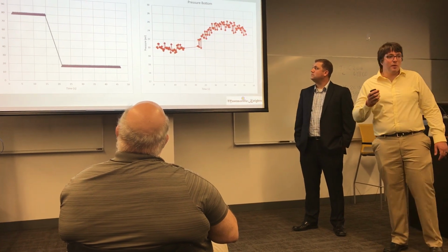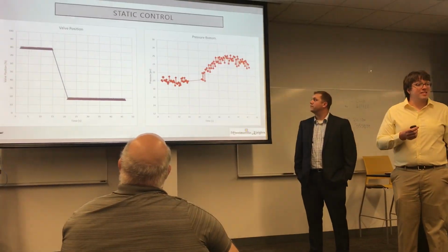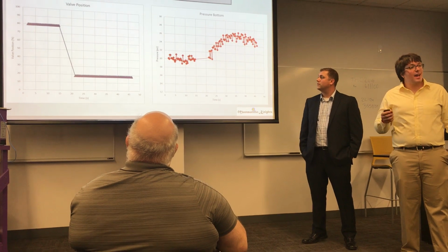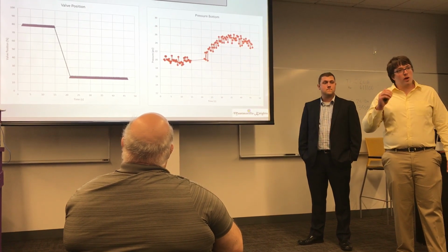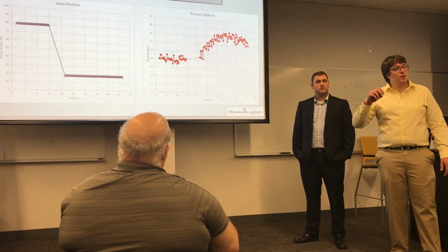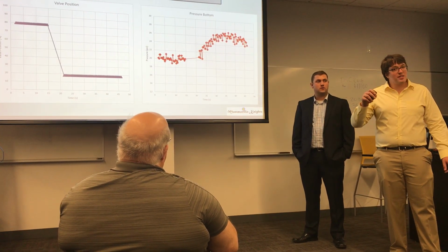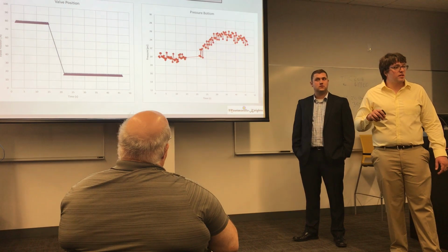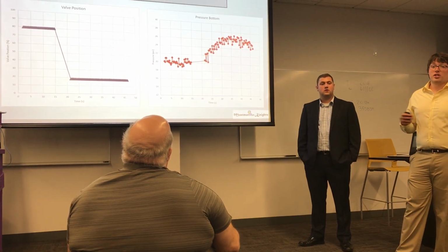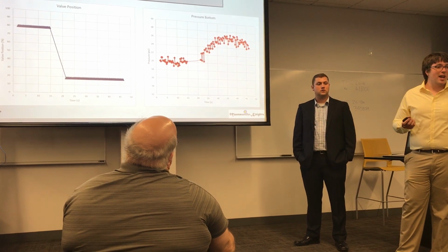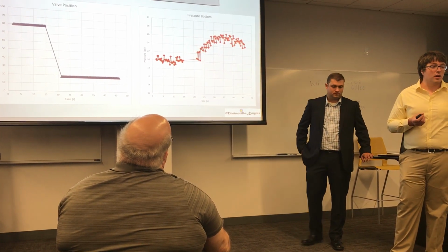Okay, so we talked a bit earlier about different means of control, and one of them is static control, where we crank down the choke valve position. The idea is that if we raise the pressure in the system, we decrease the flow rate, and it's going to decrease the velocity of the liquid slugs. If we could do that, then we decrease the momentum of these slugs, which ends up being good because then we can reduce the hammering that could go on with these liquid slugs, right?